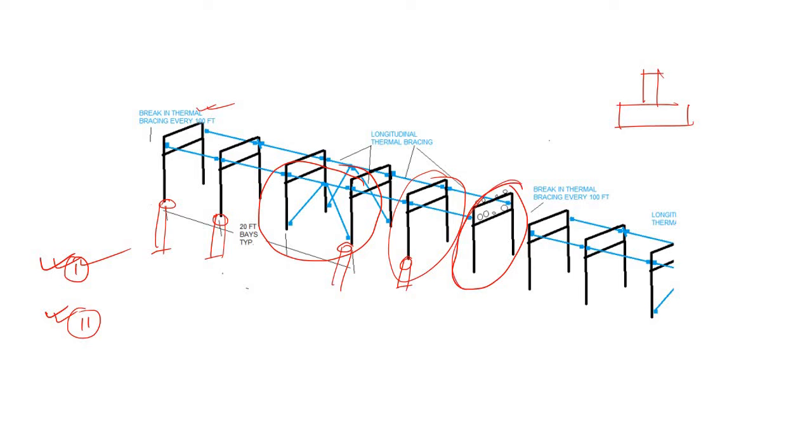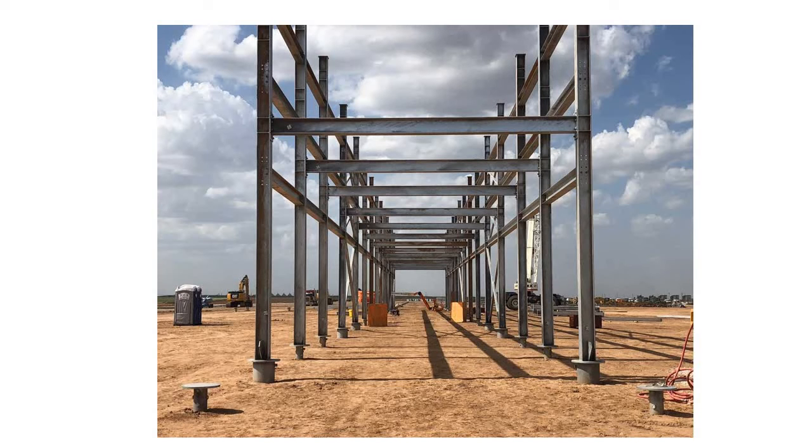So moment frame or the portal frame. This is a typical portal frame or moment connected frame, and it's a part of a pipe rack. So what are the forces acting? Well, definitely here you will have some large diameter pipes like this. So these are the pipes. You will have some vertical load like this or like this. You can also consider a uniformly distributed load, and in addition to this you may have some lateral load acting like this because of wind or earthquake load.